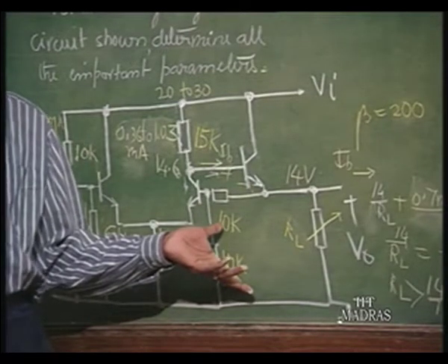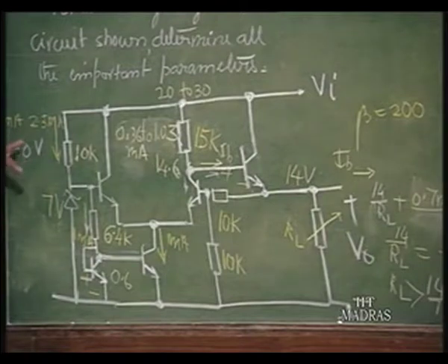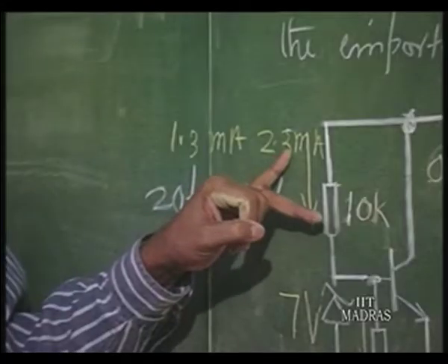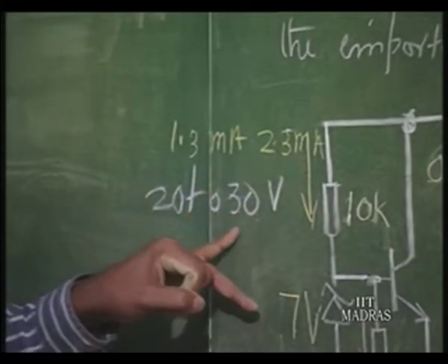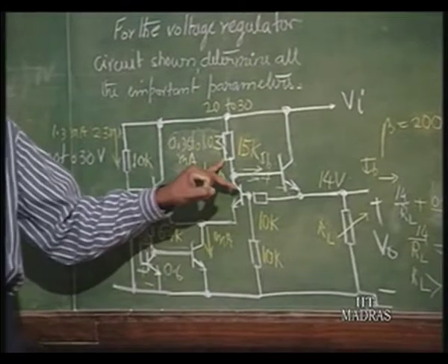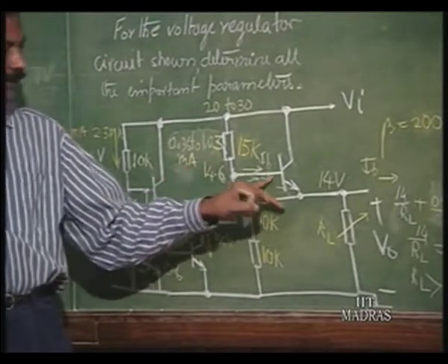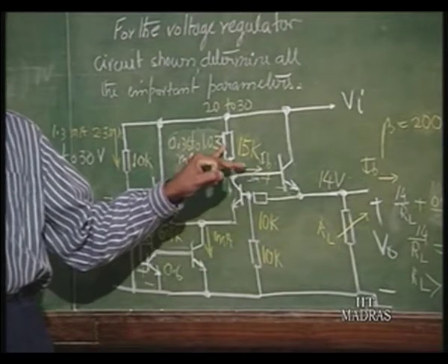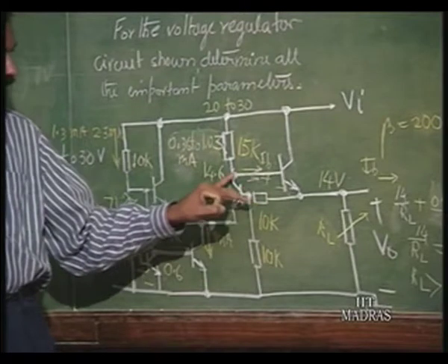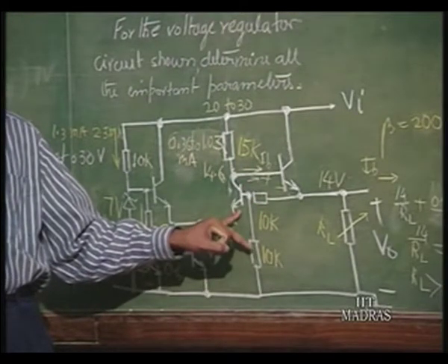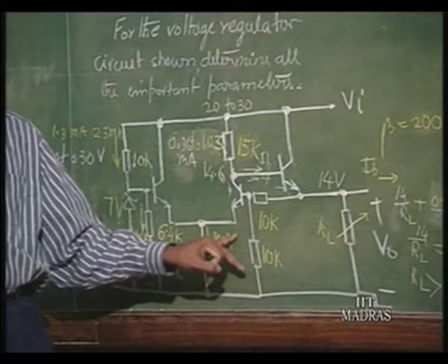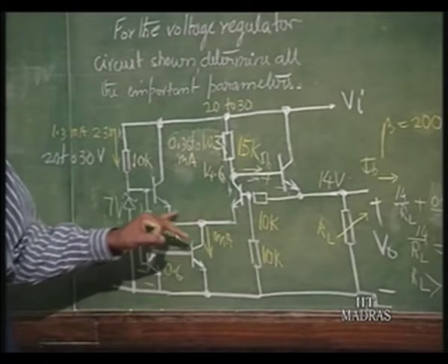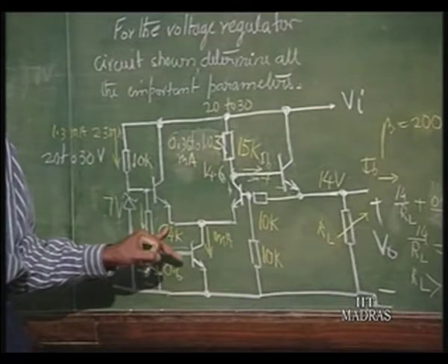Okay. Obviously, it will happily work if RL is 196 ohms with 2.3 milliamperes, that is not 30 volts, because 30 volts corresponds to 1.03 and this is demanding only 0.36, rest of it can go into this, that is 1.03 minus 0.36, whatever it is, that is about 0.64, can go into this very happily, because it still has some current to be given to this, that is 0.36, right.